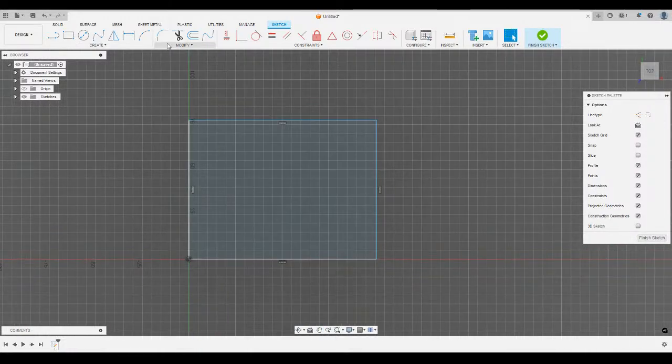And then you have your modify tools. I'm gonna do offset, for example. Well, offset's not a great example. I'm gonna do fillet, for example. With the fillet, I'm not creating something new, I'm modifying something that already exists. This is specific to Fusion and how they split it up. So I choose fillet, and now I can fillet or round over the corners of the rectangle I've already created.